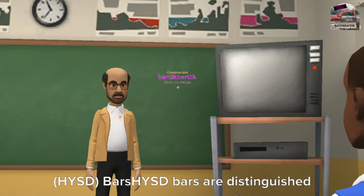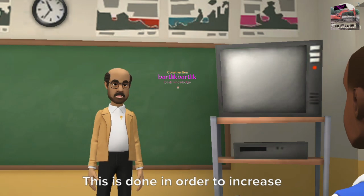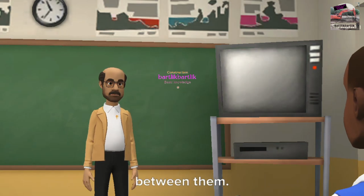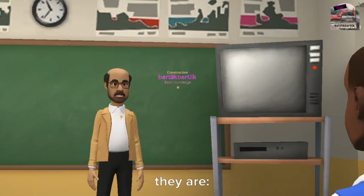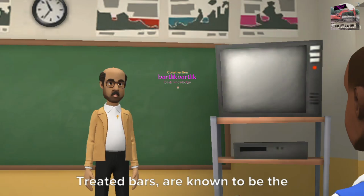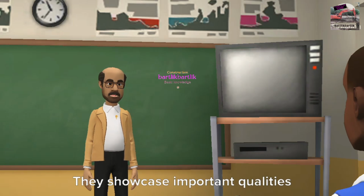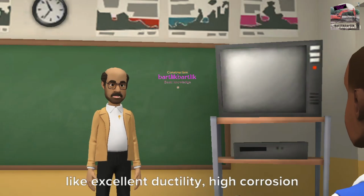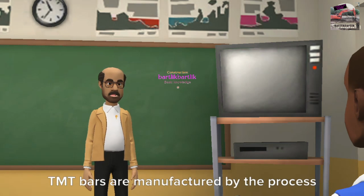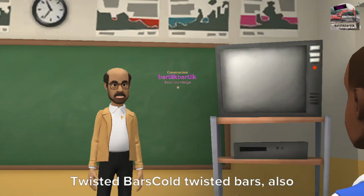High-yield strength deformed, HISD bars. HISD bars are distinguished by a ribbed rough surface on the bar. This is done in order to increase the bar bonding between reinforcement and concrete and to maintain friction between them. HISD bars are divided into two kinds. They are TMT bars. TMT bars, also called thermomechanically treated bars, are known to be the best among steel bars. They showcase important qualities like excellent ductility, high corrosion resistance, ultimate tensile strength, better elongation and better weldability. TMT bars are manufactured by the process of using hot treatment technology.